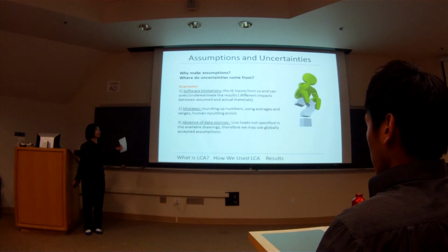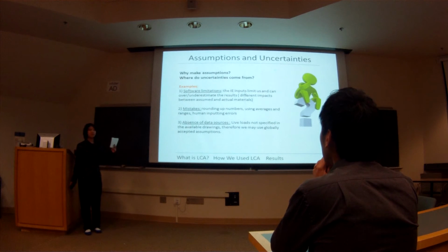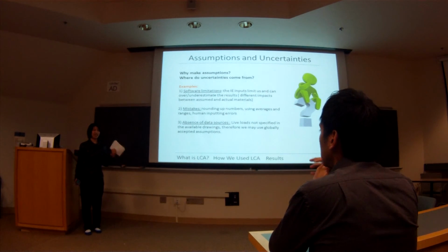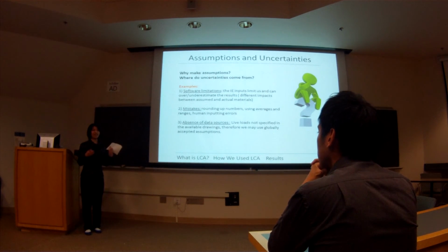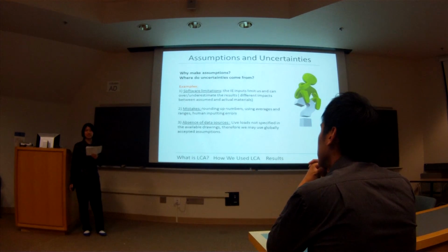And secondly, there are mistakes made at times because there are different people doing takeoffs, and perhaps one person thinks that, say, a column ends in the drawing on the outside boundary of the picture, whereas someone else might say, no, it's the inside boundary. So we would have mistakes there because of inconsistencies.